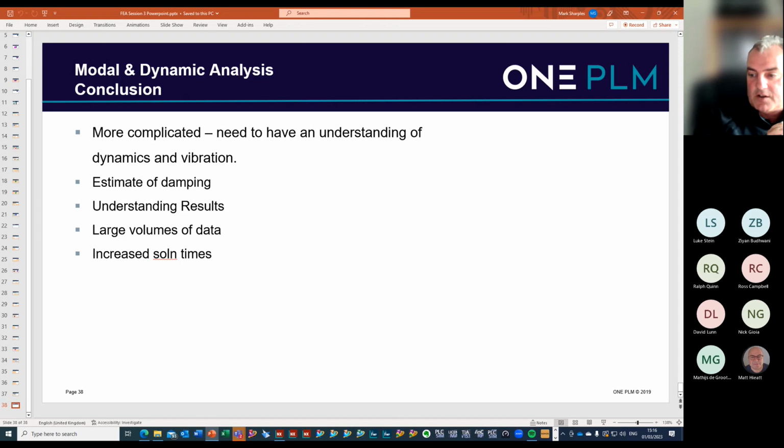You could also use your nonlinear solver, which we did in session 2, to do a dynamics transient analysis in that as well. So you could do a transient analysis, but using the nonlinear solver as a function of time, but include the dynamic effects of your structure. It's another way that you could do it as well. And how does that include damping then? What that will include is the dynamic effects of it, but I think you define what the damping parameter is in the nonlinear solver. Right. And you can have different damping for different frequencies if you want as well, I think. Rather than having the same damping for all.